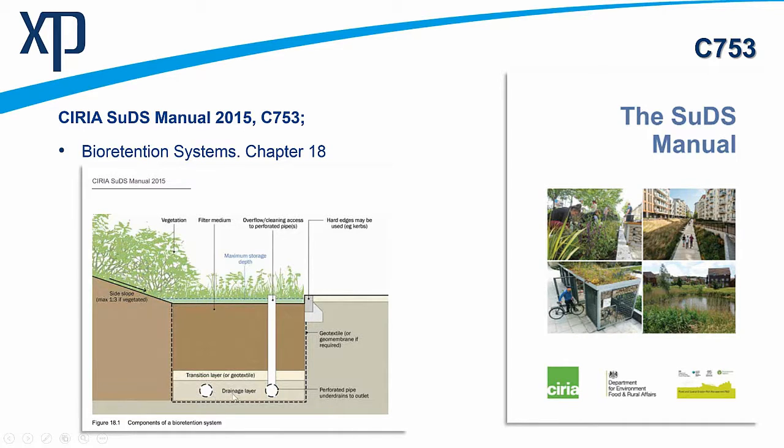If it doesn't, maybe we have the benefit of infiltrating down into the subsoil below that if the conditions are right. We could put in an overflow pipe, a vertical overflow pipe here. So when the design is exceeded, the water could then overflow and directly enter the underground drainage system and get piped away. And as I say, these can be added in or maybe not, as the case may be. So there are various permutations that we can take a look at.